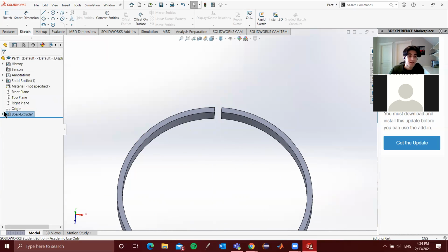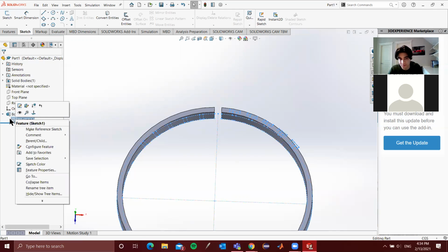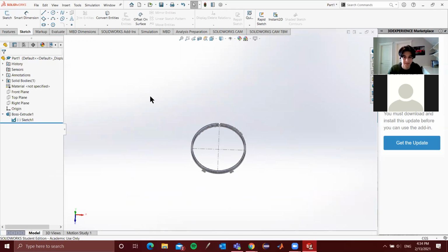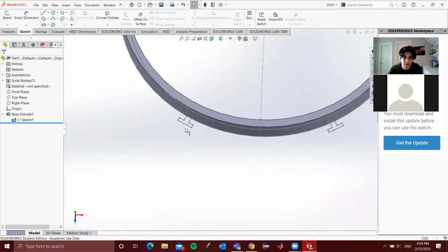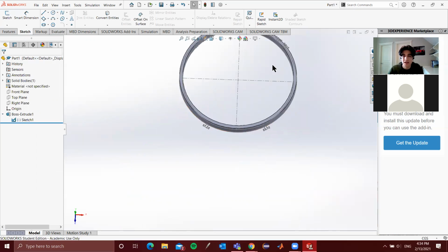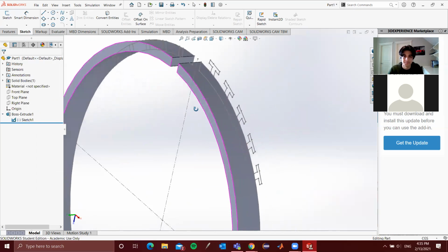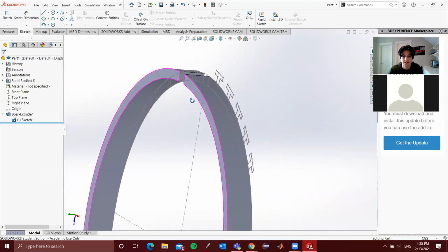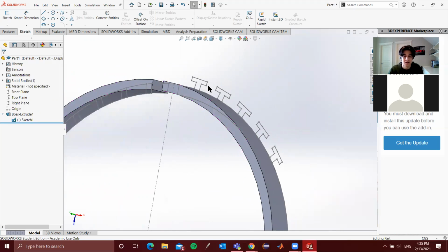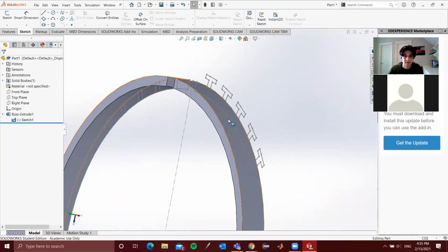So that helps out. And now we can make use of our other shapes by clicking on this down arrow here. As you can see, it's underdefined. In normal practice, you want it to be fully defined, but for the sake of this session, it'll take too much time. So that's something I recommend trying out at home. But we have all of our different contours here. So there's a couple of different functions we need to do, and I'll show you how to do them. So first, let's extrude these little sort of T sections here.